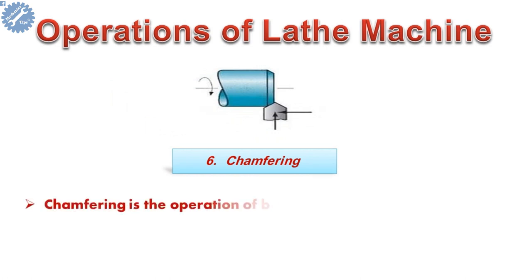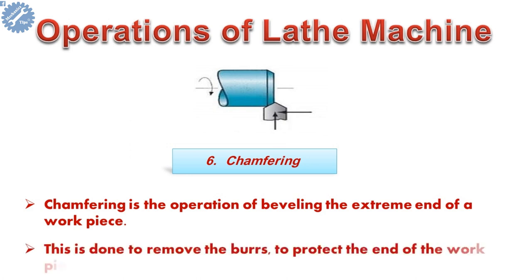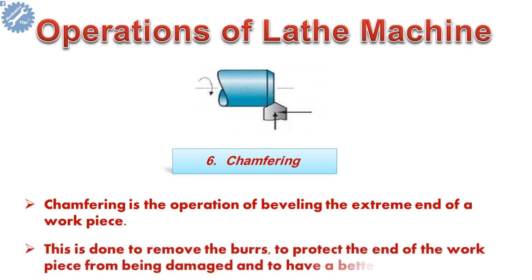Chamfering is the operation of beveling the extreme end of a workpiece. This is done to remove burrs, to protect the end of the workpiece from being damaged, and to have a better look.